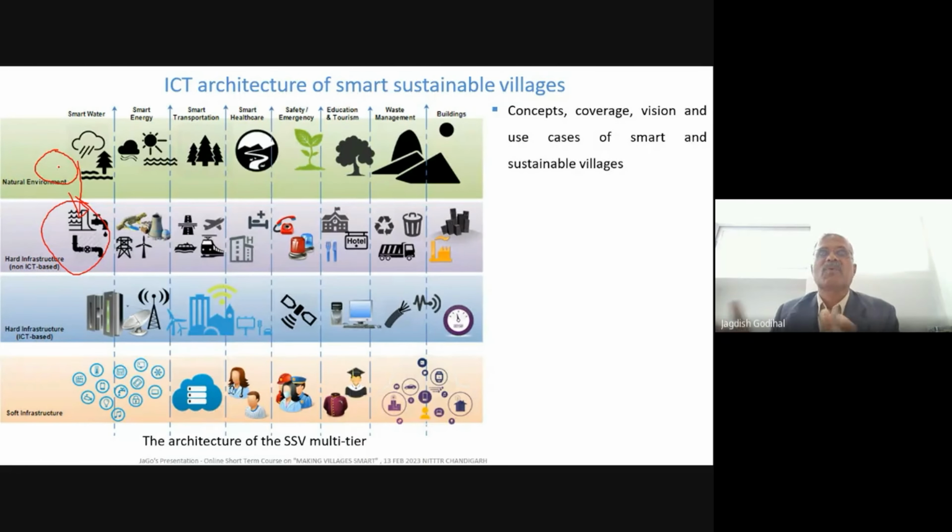So that means again here I'm going to use the ICT tools. I will monitor the water quality, raw water quality. I will adjust my treatment, different units of the treatment, as per their nature and degree of the treatment required. I'm going to set the sensors, and then I'm going to fix what will be my potable water quality parameters. Here my potable water quality parameters will be monitored, and then they are going to change season wise, because the turbidity in the natural water in the summer will be less, whereas in the rainy season it will be more. Accordingly, my sensor senses, and accordingly there will be a change in my degree of treatment.